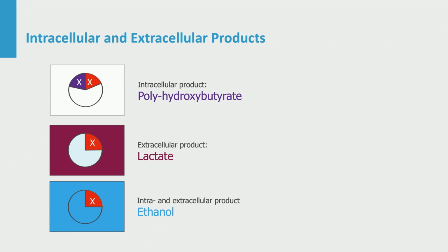Products that consist of small and uncharged molecules, such as ethanol, but also PDO, may spontaneously and quickly partition between intracellular and extracellular liquid. After separating extracellular liquid from the cells, thorough washing of the cells will also remove the intracellular portion of the product from the cells without cell disruption.